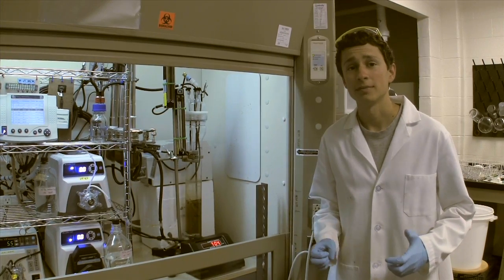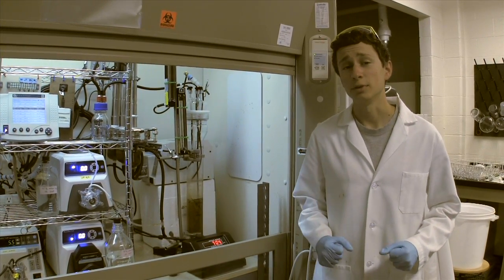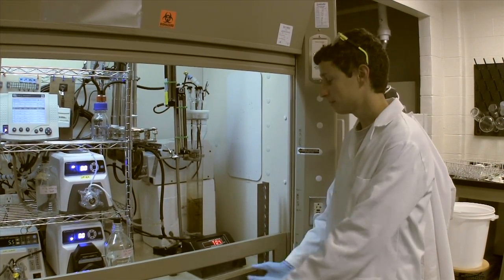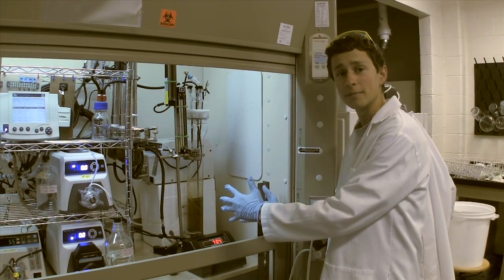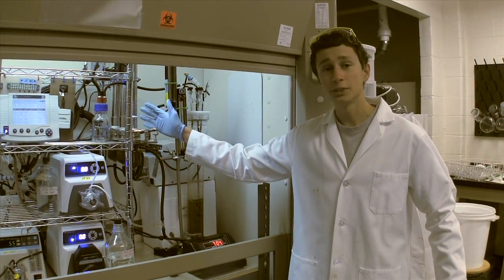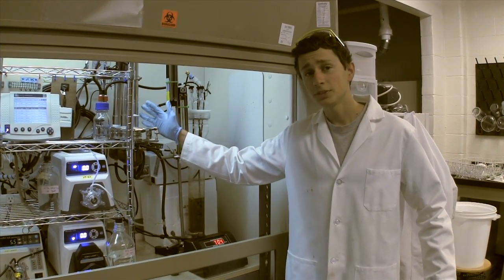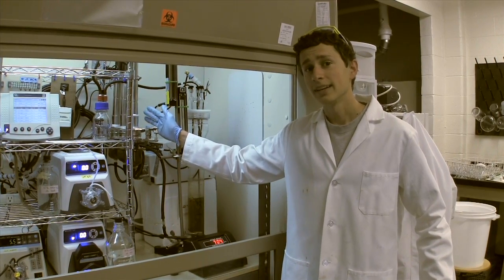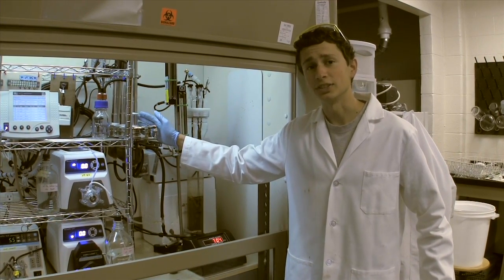The anaerobic stage provides favorable growth conditions for the anammox. Like for the MBFR, a synthetic anaerobic effluent is fed up from the bottom tank into the SBR. Up here we have a series of probes which measure the pH, the dissolved oxygen, and the nitrate/ammonia concentrations in the system.